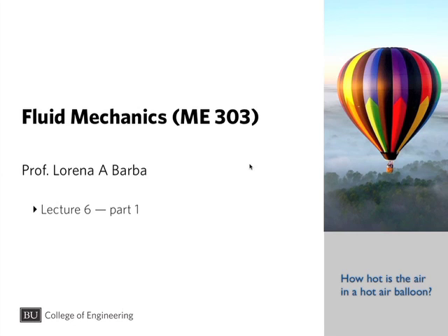Basically it was the application of the hydrostatic formula to calculate forces on submerged bodies. The first approach was simply a rectangular, vertically oriented surface. Then it incrementally gets a little more complicated: a trapezoidal shape, still vertically oriented, submerged in water.